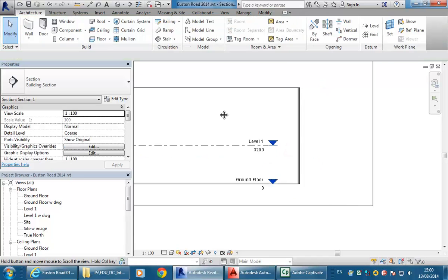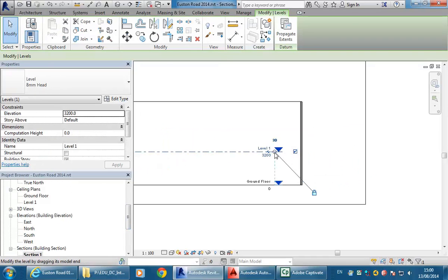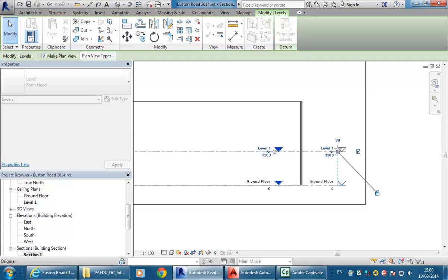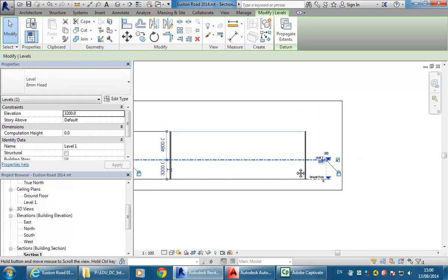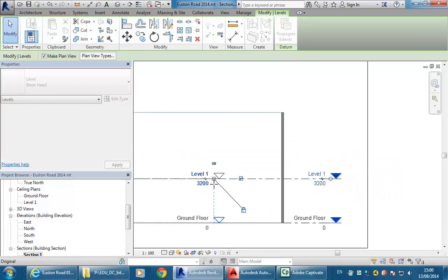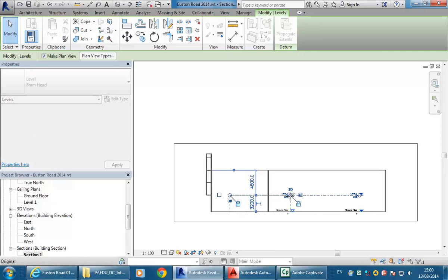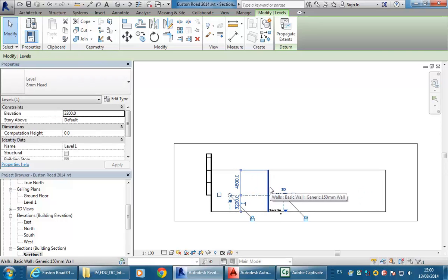And if you missed it, I've just opened up the default section view there. I haven't made any new sections or anything like that. I'm then going to just drag the levels out, and that's another tip I can give you. If you get your levels set to the extents of your project, oh no, I've gone the wrong way, sorry, back here. Right, so thinking again about the extents you're going to be working with, here I've modelled in that part of the warehouse that you aren't going to work with. So we don't need the level to go that far. I'm going to bring it right back so that it's close to this rear wall, which is the extent you have to work with, and then I'll drag the front out as well.